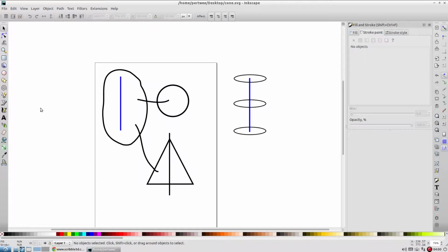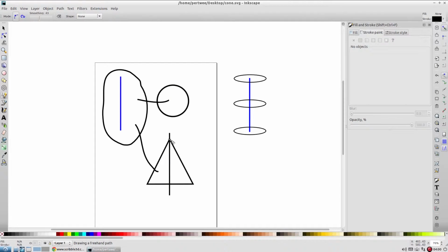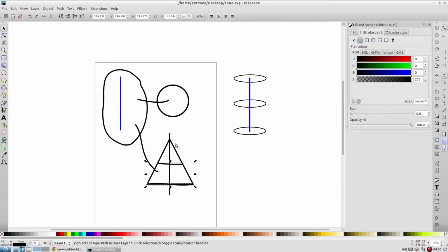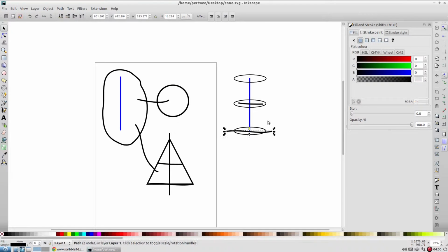The next step is to extract the width data from the silhouette path and the width line. Width is extracted by lines drawn perpendicular to the width line, intersecting the silhouette. Now scale the cross-sectional slices proportionately, corresponding to the extracted width at each point.